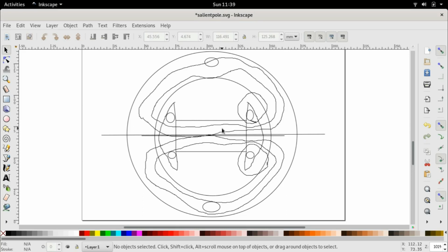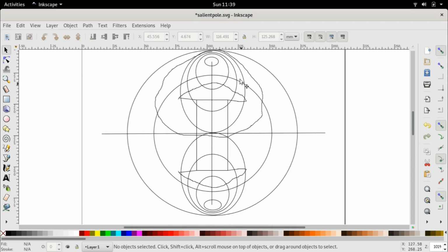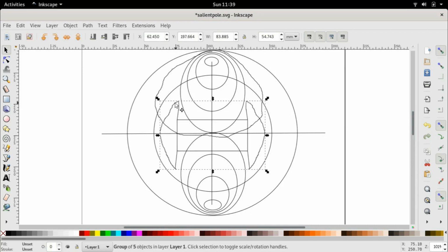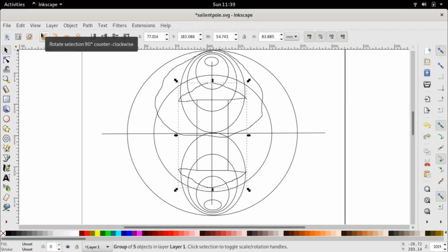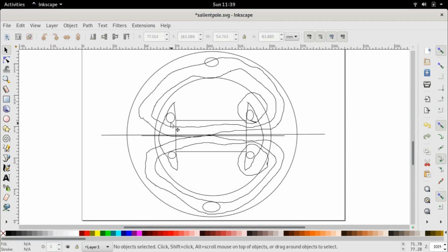The air gap does not change if I rotate it. This is totally different with respect to the stator flux. Now if I take this stator flux and rotate this rotor, you will see that the air gap for the stator flux is changing drastically. Look at the flux here. It is totally different with respect to the flux in this position. Whereas here you see that the air gap for the flux has not changed.